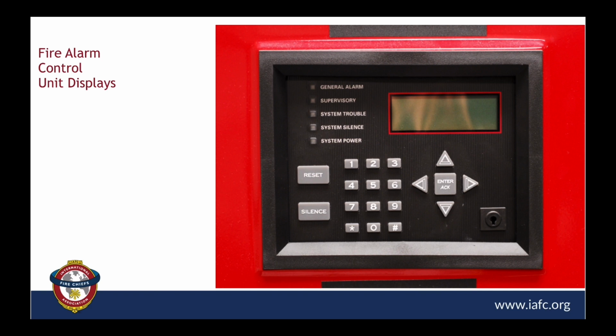It will give you the type of device it is, and it'll let you know where this is located. So this is an addressable type of system here. When you walk in, you're going to see device 01, smoke detector, Chief O'Brien's office, first floor. That's the kind of information that'll be on the display. You'll be able to look to see that it's an alarm condition, which means it's a fire of some sort